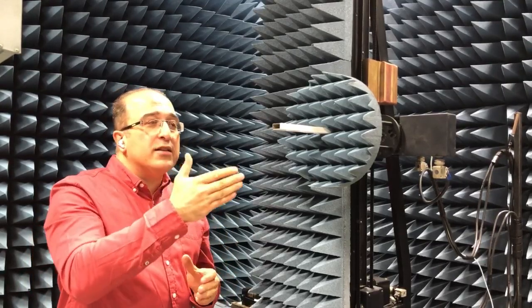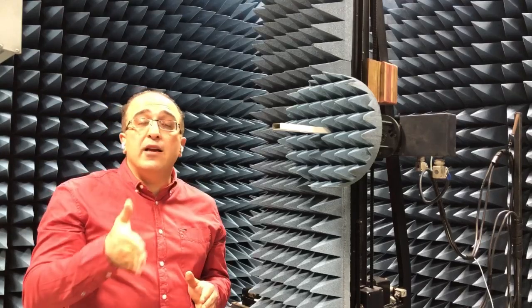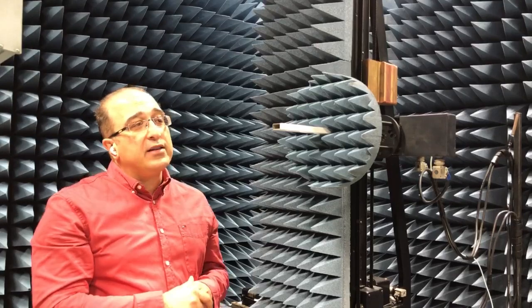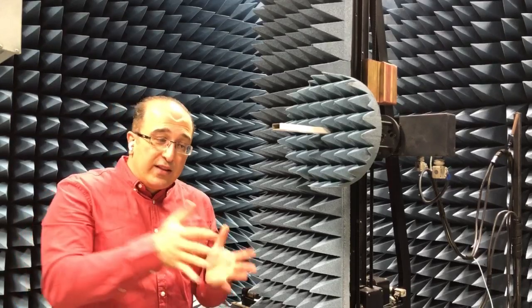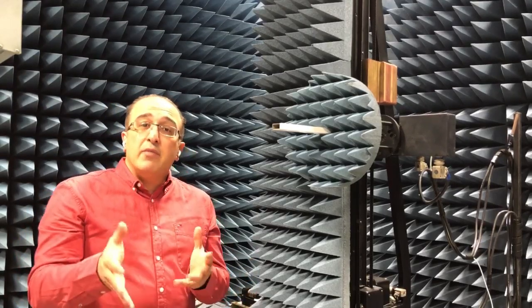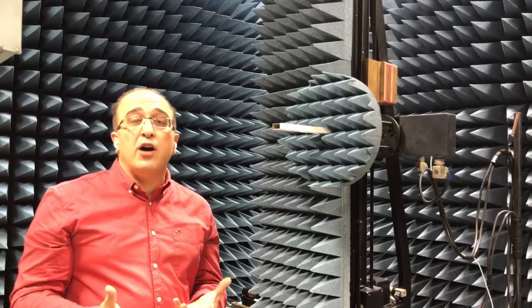So as I mentioned, this is working above a certain frequency. For example, if you want to work at a lower frequency, you need to change your waveguide. For example, this waveguide that I have here is ideal for X-band, which is approximately between 8 and 12 gigahertz. Now, if you want to be working at lower frequency, then you need to change your waveguide, because the smaller the frequency, remember, the wavelength becomes bigger. Everything is with respect to wavelength, so the waveguide becomes larger.